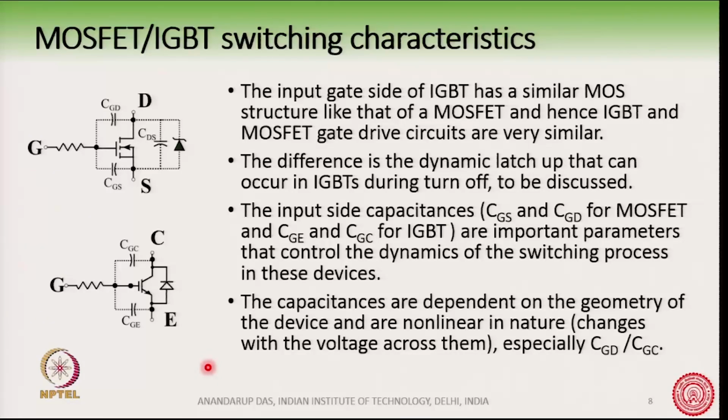The gate drive circuits or the analysis for the gate drive circuits are more or less the same for both IGBT and MOSFET. There are some differences, of course, like there is a dynamic latch up that can occur in IGBTs during turn off, but relatively speaking they are very similar. The gate drive circuits for IGBTs and MOSFETs are very similar and they can often be interchanged. Now, the input side capacitances.